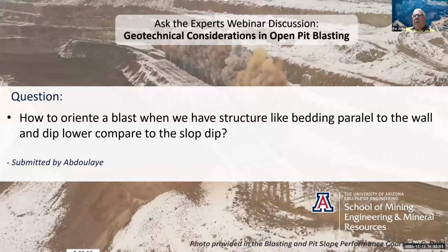Things like reducing the amount of gas that's generated from the shot, providing relief, someplace for a trim shot to go so that gas pressure doesn't go up into that bedding and dilate that bedding even more and make the situation worse. But you really have to give it a lot of thought. And that's something else to consider in addition to what Ray identified.